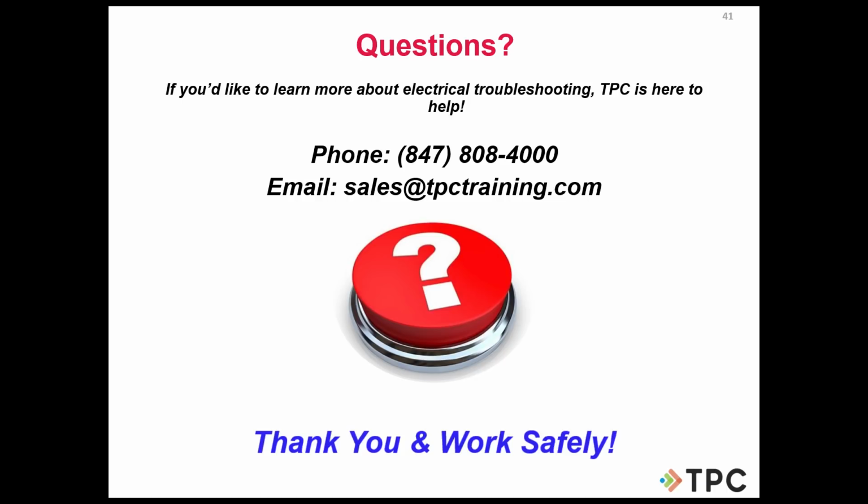I wish I could in only 5 minutes, but I would say that when it comes to motor troubleshooting, make sure you have a category 3 meter and that the motor is completely de-energized. So what we say in terms of troubleshooting motors is, if at all possible, make sure you can do some of the electrical tests on this motor when it's completely disconnected from electricity, right?